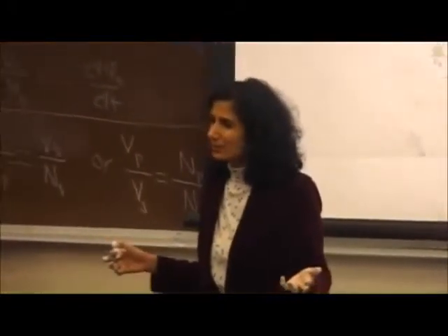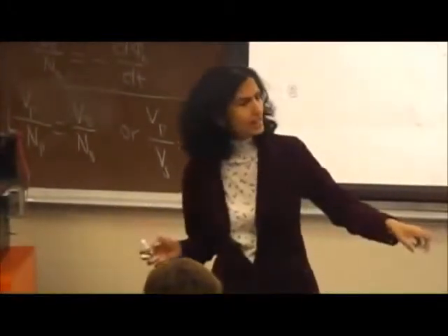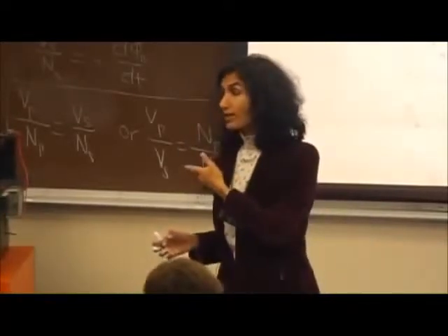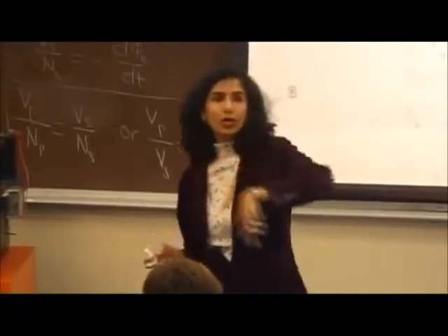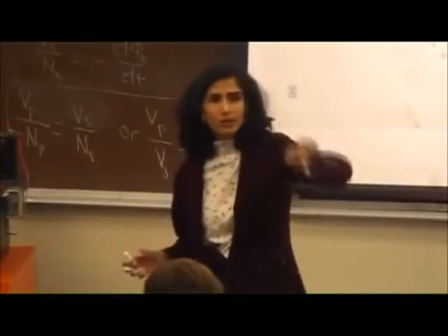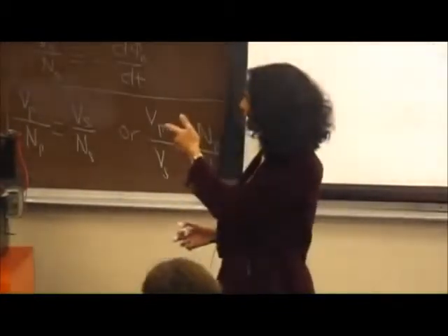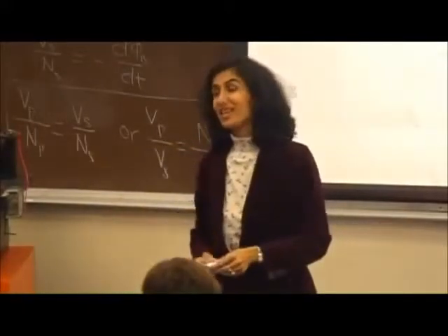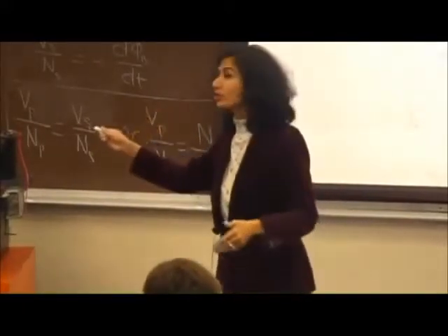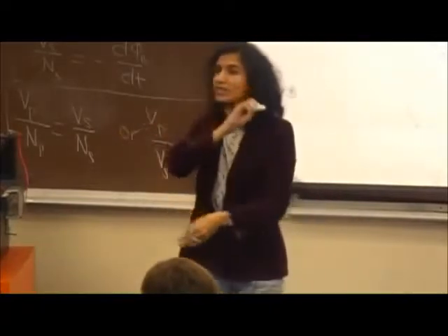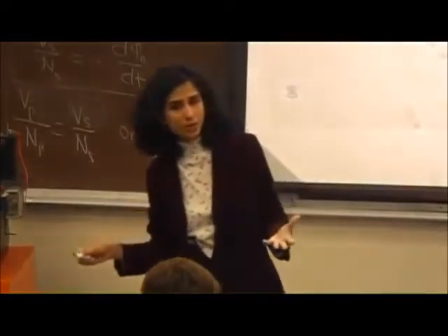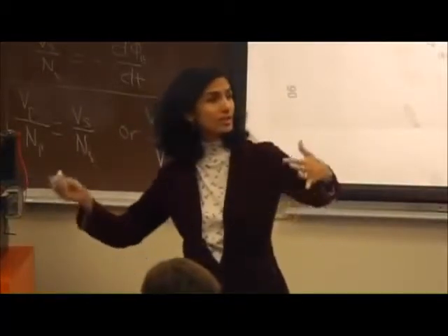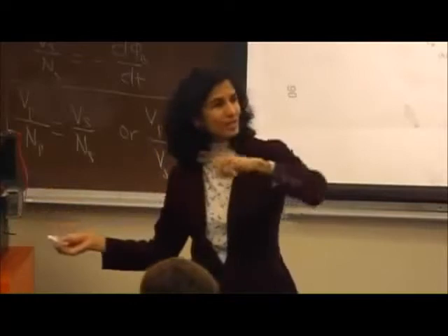Why do you think that will happen? In the theoretical case I'm going to talk about right now, this is not what we'll see. What we'll see is that this oscillation will keep going forever. What is there in that circuit that is not there in my model here? Resistance. It's the resistance that's actually going to decrease the current in that circuit, because the resistance will lead to power dissipation, right? I squared R, and that means electrical energy is going out of the system in the form of heat, and soon you will see that it will get damped out.